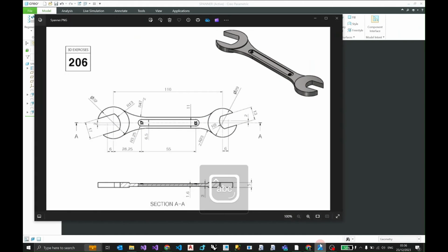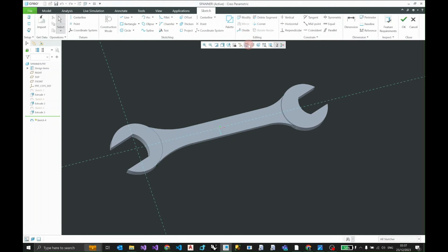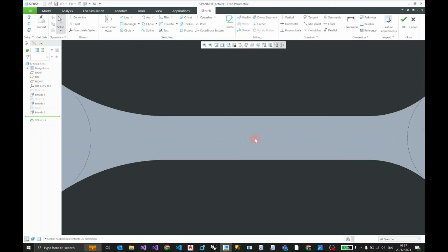The next thing we notice over here is the numbers as well, and this recessed surface, which is 1.6 millimeter across, which means that from this surface it is 0.9 under. The removal of material is at a depth of 0.9. So I'm gonna again select this surface, enter the sketching mode, give it a normal view, and I will again make this geometry.